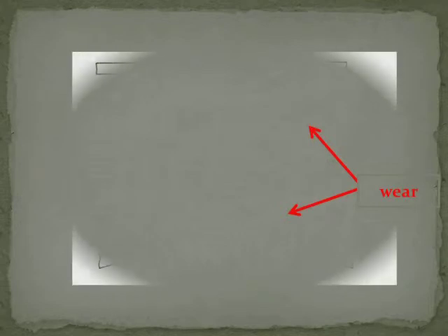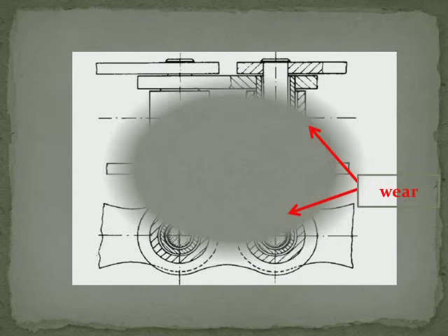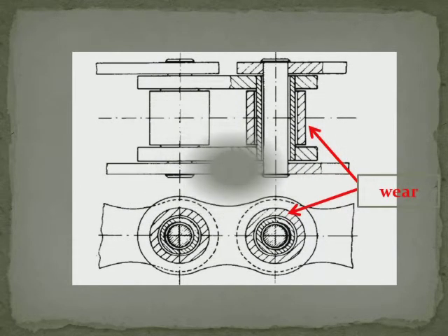Next, we go to roller chain wear. There is less attention to the wear problem of the chain. There is no experimental result for wear measurement for roller chain because it requires a great expenditure of time and work. Normal chain wear is caused by stretch of pins and bushings when they enter and leave the sprocket. In the figure, the surfaces of the pins and bushings are marked in black.